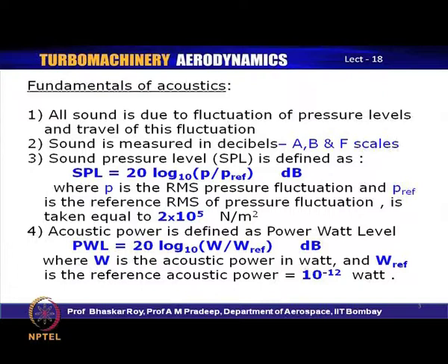Sound is typically measured in decibels. This has been derived over a period of years, and it is measured in a number of scales, predominantly in A scale, sometimes in B scale. There are many other scales which I will mention, and finally, F scale, which is called the flat scale, and I will mention very briefly what these scales are a little while later.